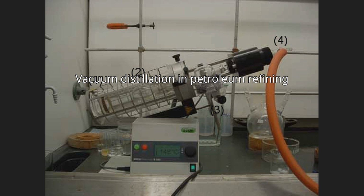Plugging would also occur in the piping from the furnace to the distillation column as well as in the column itself. The constraint imposed by limiting the column inlet crude oil to a temperature of less than 370 to 380 deg C yields [a residual oil]. To further distill the residual oil from the atmospheric distillation column, the distillation must be performed at absolute pressures as low as 10 to 40 mmHg/torr, about 5% atmospheric pressure, so as to limit the operating temperature to less than 370 to 380 deg C.